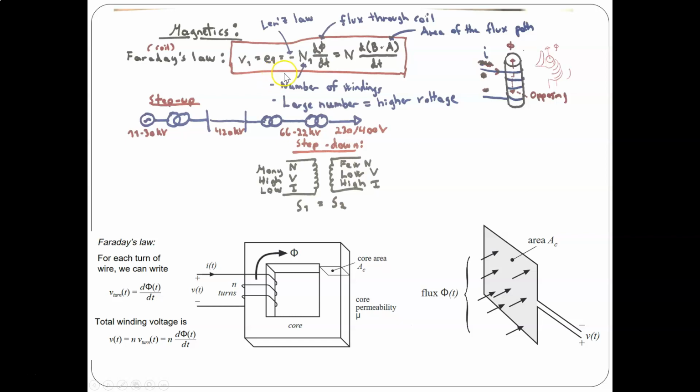It is a phenomenon known as electromagnetic induction, and it equals the number of windings times the derivative of the flux, the flux passing through the specific coils. It also has a minus here, you note Lenz's law. So it produces an opposing force when the flux is passing through the coil.